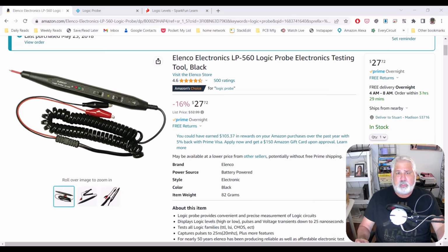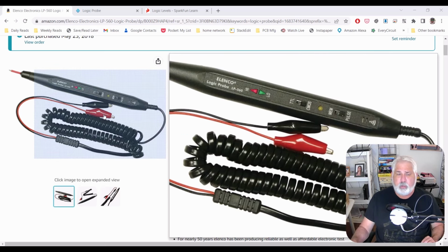Well, in the simplest terms, what you are doing is looking at logic signals, highs and lows, on digital circuits with it. You're going to hook it up with these clips to the same power supply as the digital logic circuit that you want to check on. You want to check values. You're trying to debug or repair something, and/or you are just analyzing how something works, let's say.